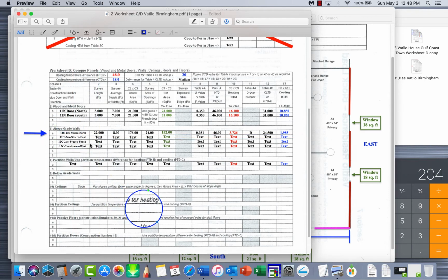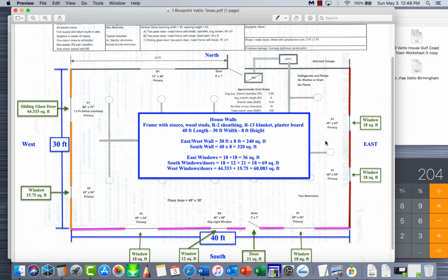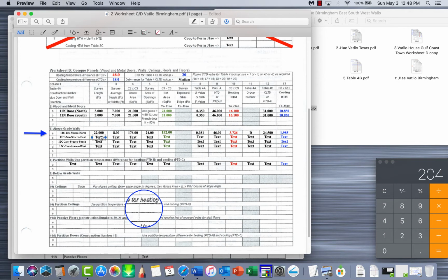So we're going to be right here. And we're just going to move across through here, get all the calculations, do all this one, go all the way across there, get the calculations, go this one here, do all of them, go all the way across, get the calculations. Now, like I said, we can still kind of see it from here behind the page here, our total wall footage and length and width. So we got 30 by 8. So east wall is 30, 8 feet tall, and this is one of those where I know every wall is 8 feet tall, so I'm going to go ahead and put that in there. Okay, and I know the west wall is 40 feet, and the south wall is 40 feet, and the west wall is 30 feet as well.